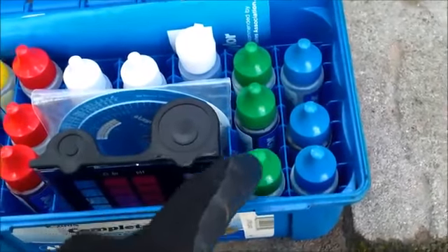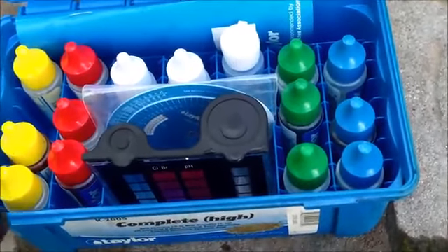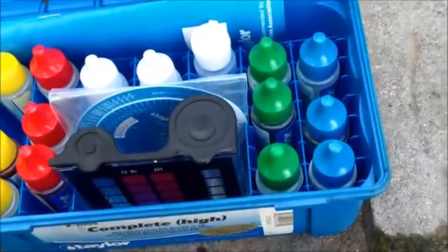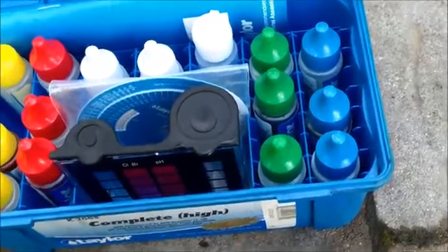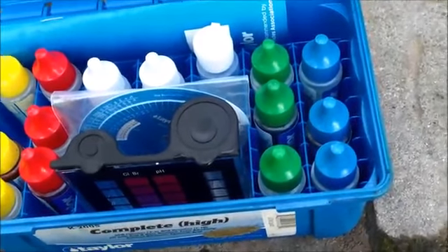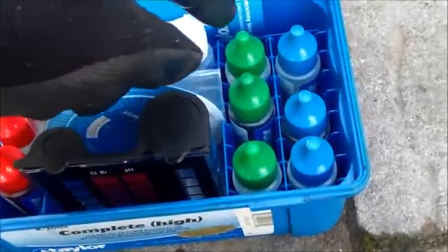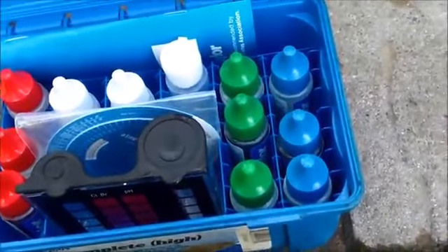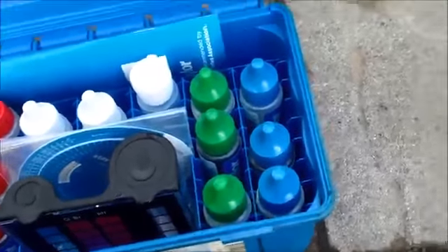So the alkalinity level is important. It controls how the pH reacts in your pool. It's called pH bound. So if your alkalinity is too low or too high, it could affect the pH in your pool, and also the plaster or the surface of the pool can be affected by that. And your calcium hardness also affects the water's hardness and scale level.